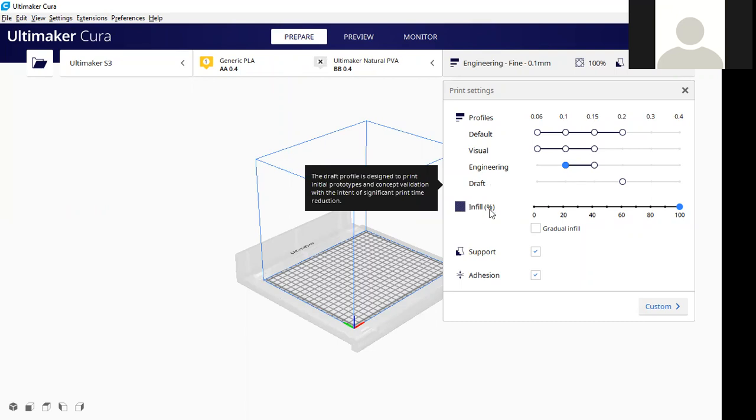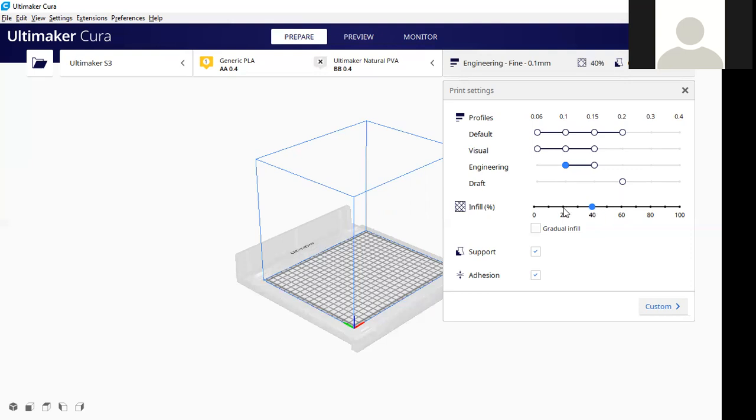All right. Next, we have the infill. Infill is the pattern of deposition of your hot filament. Okay. And you have infill from 0 to 100. 100 is more like a solid block. Then as you reduce, watch this space, you see 80, 60, 40, 20. All right, you can see that there are changes.